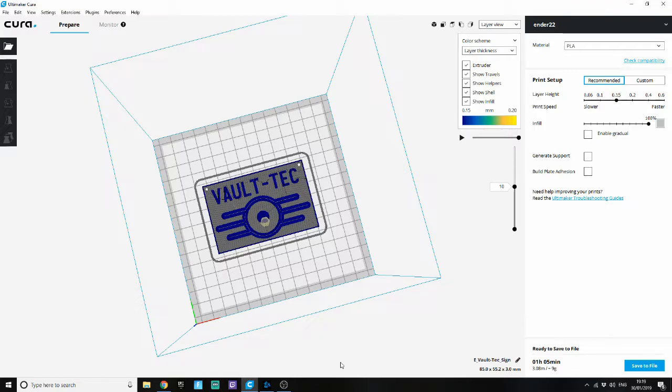So then all you want to do is scroll down to print from SD card, select the file that you want to print, and then it will just go back to the main screen after you've pressed that. And then if you press it again, you'll have an option to tune. And once you've tuned, I always change the nozzle to 205 and the bed to 60, and always just at a straight 100 for speed.